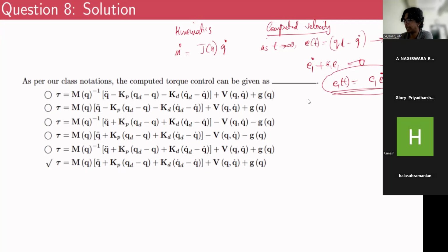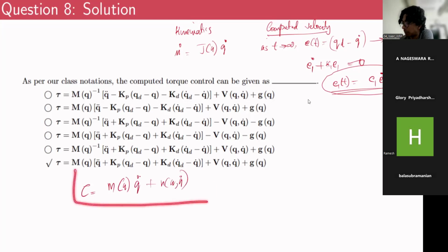I don't know the entire equations, but basically, you will be deriving the entire dynamics of a mobile robot, right? That will also have a similar equation, something like this. Tau would be M of q multiplied by q double dot plus N of q dot. I believe he's deriving something of this form in one of the lectures.